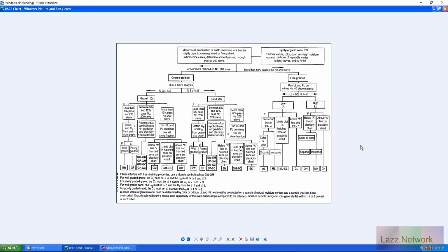Remember, back in the first video for Atterberg limits, everything is just a moisture content to get the values that we need for the test. So silts can't hold as much moisture as a clay can.